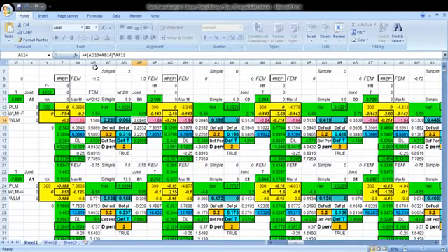So AG13 is this plus this one which we got here, 1.588. AB14 means this joint pulls this value here, and we sum up this, and multiply by AF13, and AF13 is the rotation contribution factor. Now we go further, we get value here.